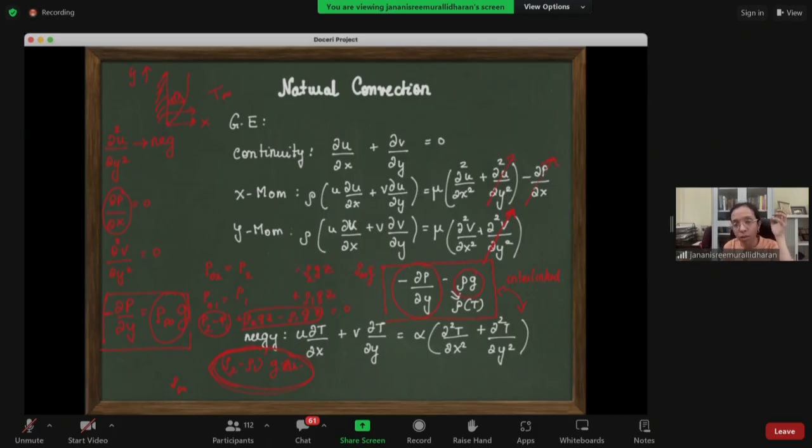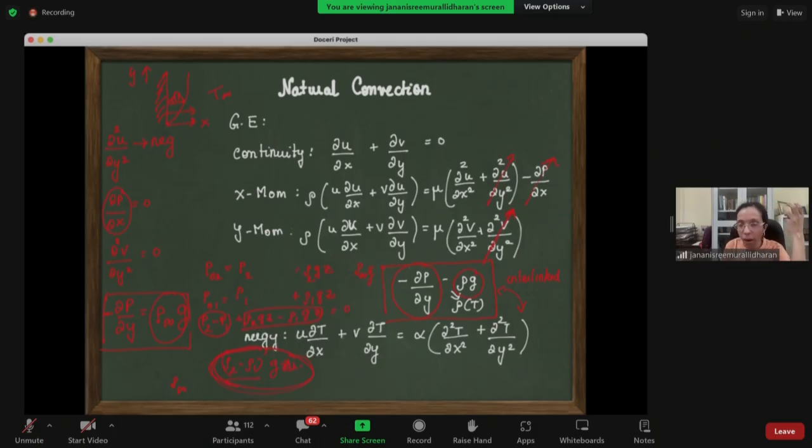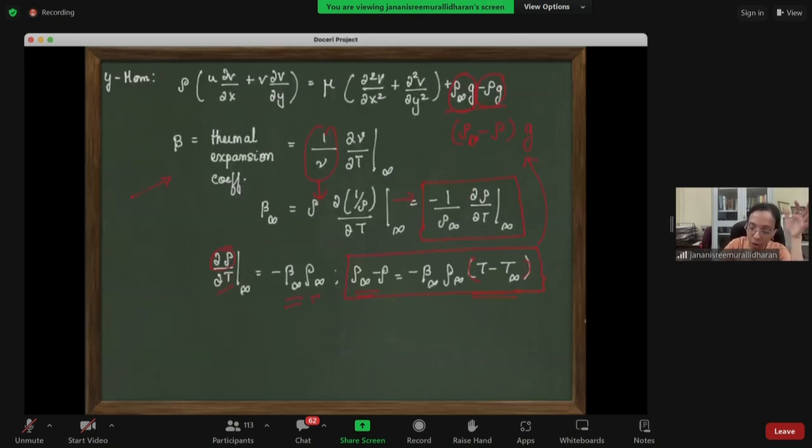Denoting the difference caused by the density and the gravity effects, right? Now, this is not the full effect, correct? When I'm writing it as ρ g, there is actually a pressure term also involved. The actual difference is that the pressure difference causes flow. Flow is happening only due to the delta ρ into g. So this is only one part of the ρ. So we are bringing in this ∂p/∂y as a ρ infinity, which is the actual ambient density, and that difference together, clubbed, is called the Boussinesq approximation. And that we are now writing in terms of temperature using the thermal expansion coefficient definition.